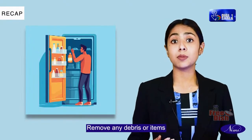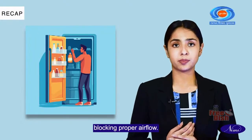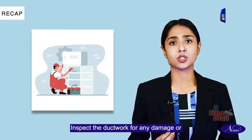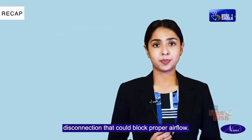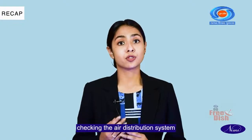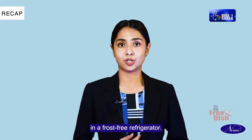Remove any debris or items blocking proper airflow. Inspect the ductwork for any damage or disconnection that could block proper airflow. I hope you all understood the processes of checking the air distribution system in a frost-free refrigerator.